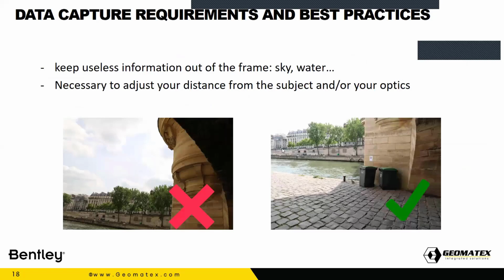Some tricks, if you want to take a reality model: please don't get very, very close, and also avoid having maybe more than 50% or 40% of the image be sky. Try to use an angle in which you are getting some features to add texture to your image.